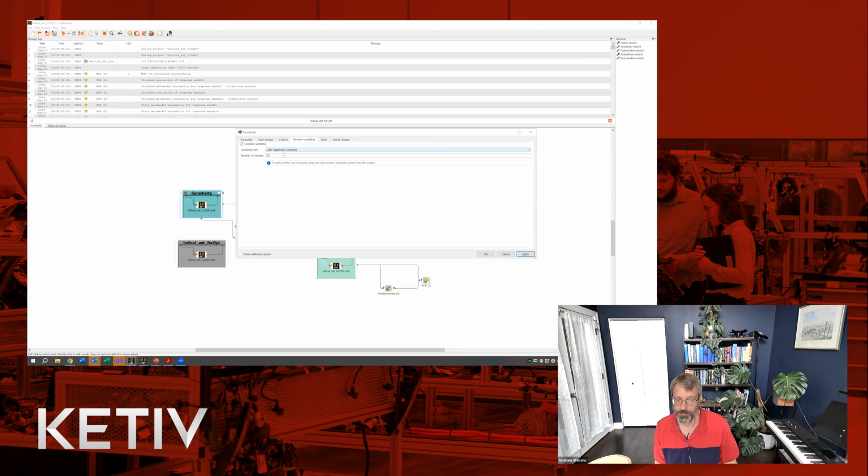So we say Latin hypercube sampling and number of samples. We look at the parameterization. In this case, I did discrete by variable for these helix terms, 7 through 10, but not any partials. Set up a criteria if we have an objective. In this case, I want to maximize my gain, and so forth.